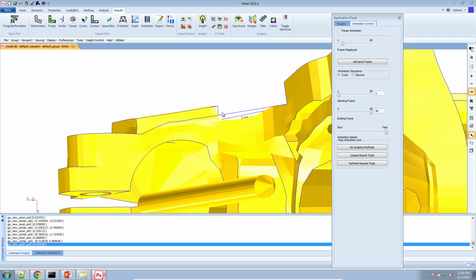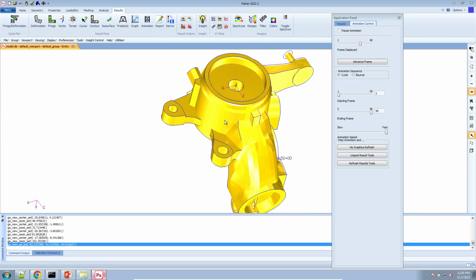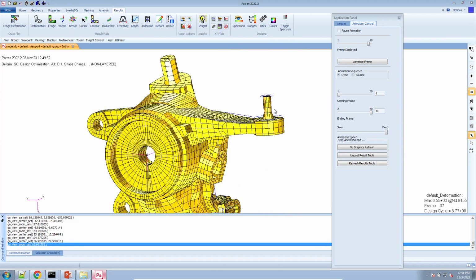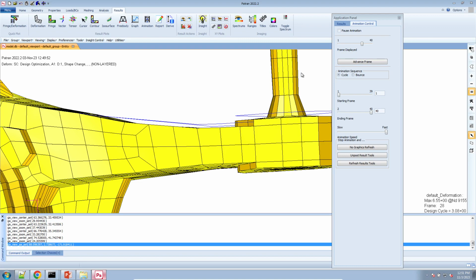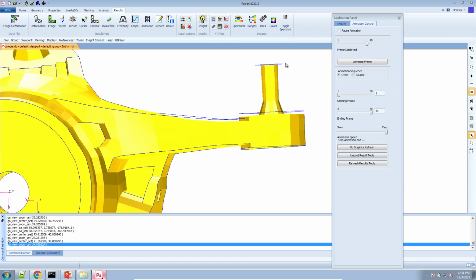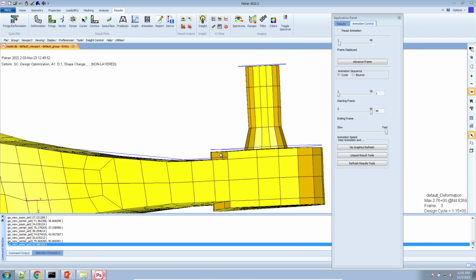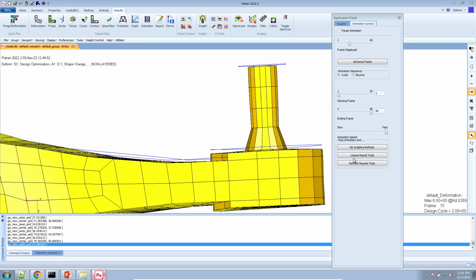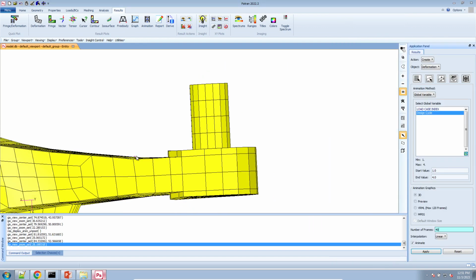Now, the same can be said for this other region where we change the shape. So let's go ahead and look at this. So here we were able to actually contract these 2 shapes to minimize the mass in this region while making sure the stress is within our specified bound. Now, what is there left to do? We need to make sure that the stress value is under the upper bound of 40. So how do we do that?